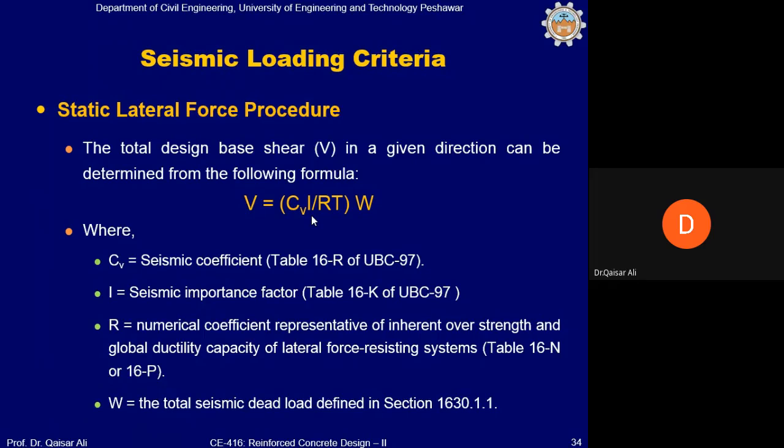So for masonry structures, R must be kept less, so that they are designed against such forces which would ensure life safety. So the greater the R, the more efficient the structure, with more controlled damages and less base shear, giving an economical structure.